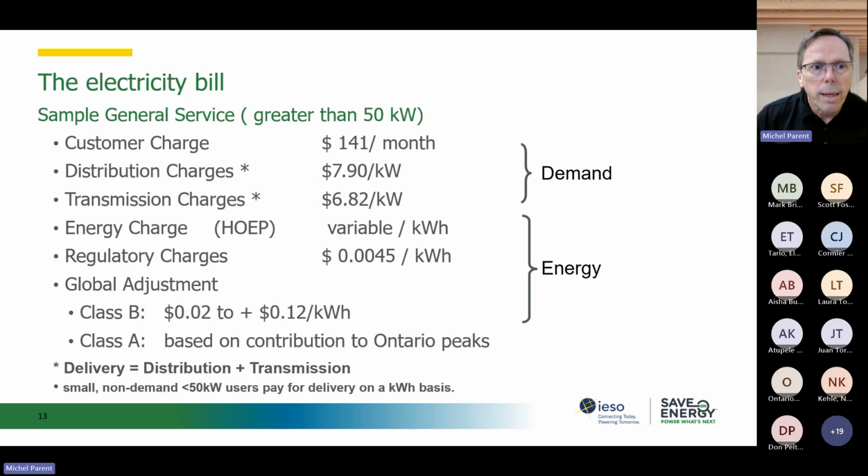And you always pay the energy of a heat pump at the marginal cost of your electricity. So 10, 14 cents for a Class B. A Class A, that's where it can make a big difference. You pay your global adjustment on a kilowatt basis, coincident with the 5 peak hours in the year, which are currently mostly in the summer, but your energy cost will be much lower.